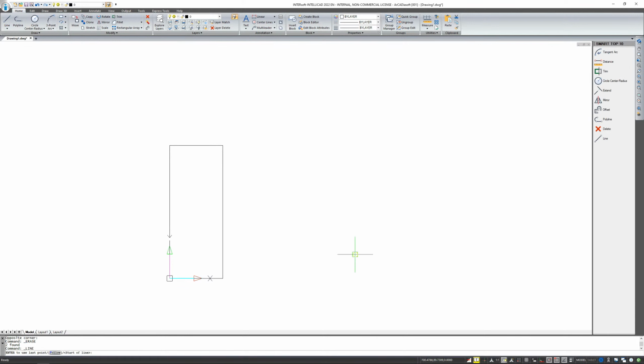The first value is exactly the same, but now when introducing the next value, remember that you're starting with an at sign again, but now this is the beginning of the coordinate system, which means that if I draw up, for example in x, there will be no displacement. So I start with 0, the comma, the value in y, it was 500. And in this way, every time starting from the at sign, I enter the appropriate data relative to this exact point. So now again, when it comes to the horizontal element, it will be to the left, which is minus 200, comma, 0, because I'm going horizontally.